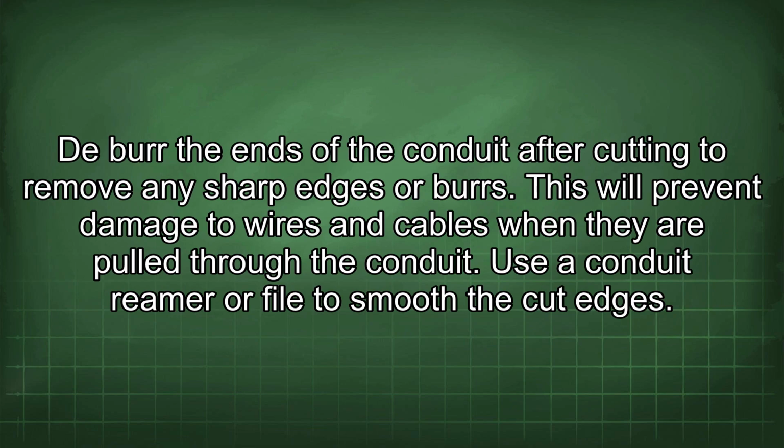Deburr the ends of the conduit after cutting to remove any sharp edges or burrs. This will prevent damage to wires and cables when they are pulled through the conduit. Use a conduit reamer or file to smooth the cut edges.